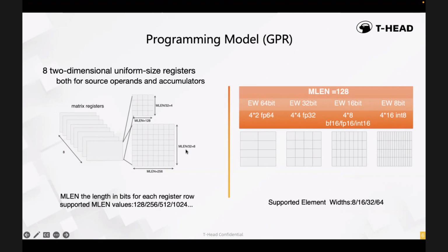Second, as we can see from many slides, almost all accumulator widths are 32 or 64-bit, no matter from ARM, RISC-V or IBM. I think they did research before doing it, so we choose 32 as the divider, and so we fix the register file size like this.